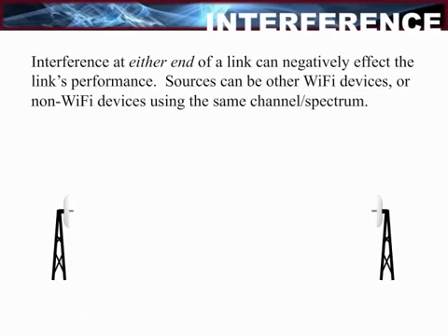Interference in RF is an unavoidable headache, and often stems from external sources. When designing RF systems, it is important to do a pre-scan of the area in order to determine if any interference exists on the channels of interest. As we will see, interference on either end of an RF link will affect the link as a whole.